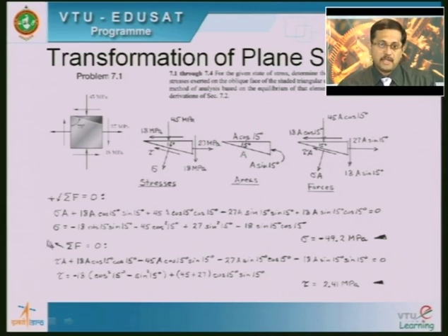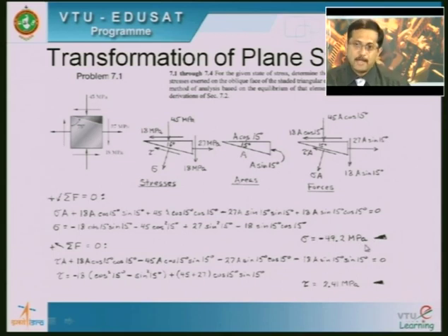So, when I take this entire equation and equate it to 0, because the algebraic sum of the forces has to be equal to 0. Everywhere you can see you have area in every term. So, I can remove that and take this sigma on the other side. And sum of all this, I get sigma equals minus 49.2 megapascal. This is what I get.